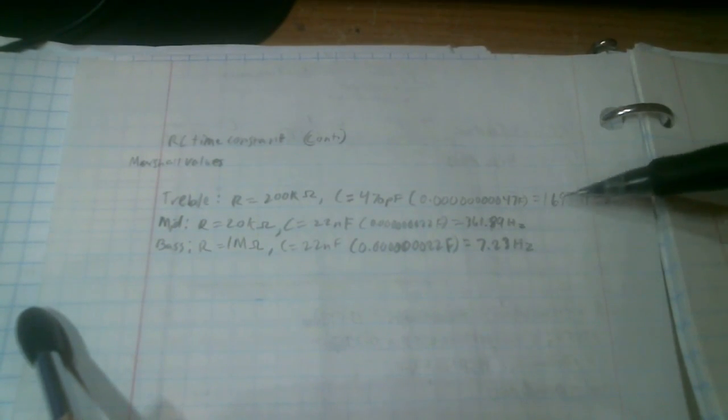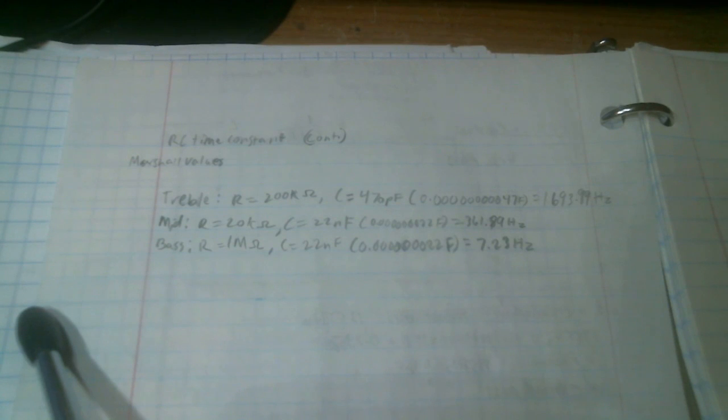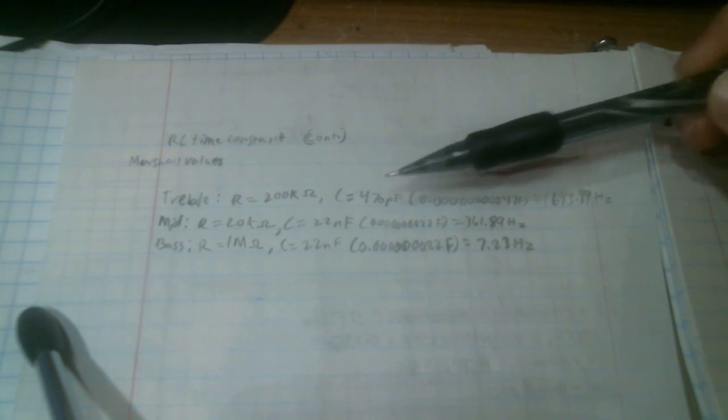The closest you'll get is 1 millifarad, and it's, well, no, maybe 4 or 5 millifarad. Because like the biggest value I have is 2200 microfarad, so it's 2.2 milli. So back over here, since I know the frequencies I want, I need to find the resistance or capacitance I need with what I have. So for instance, if I have a 47 picofarad, it's much smaller than this. It's 1/10 that.